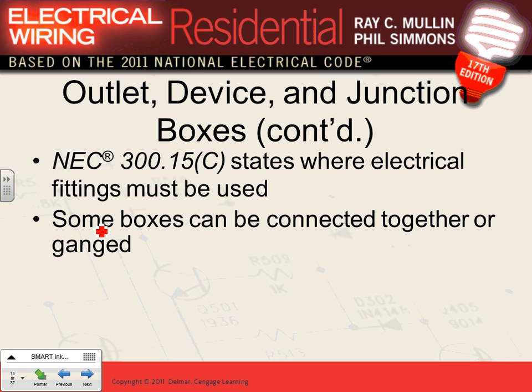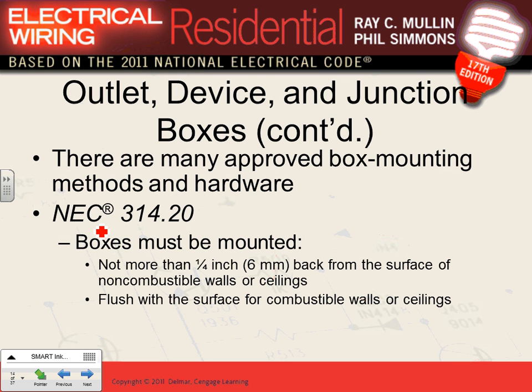There's a couple of things. Boxes also, a couple of boxes, guys, you're going to be doing. Why do we care about this one? Since you're designers, you guys are going to be doing estimating, takeoff. So boxes you can gang, metallic boxes. They can come in different sizes. So you can have a 4 gang box. We can put four devices, single gang, 2 gang, 3 gang, or 4 gang box, metallic. Or you can have non-metallic. You can gang them 10 almost if it's metallic.